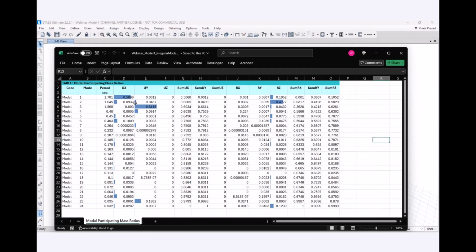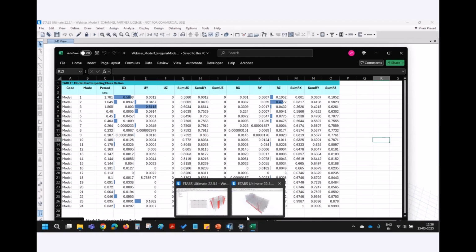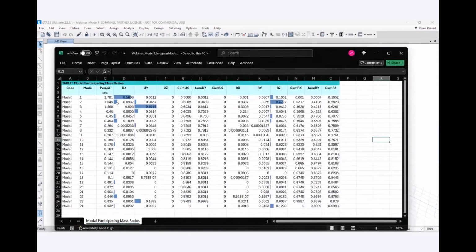to know the ranking of the first three modes in that particular direction based on the ratios. But you can see the first one, sorry, the second one is more on the torsion. This building has significant torsion. Just wanted to show a real building where this kind of situation arises. So you'll have to skip this particular mode in the summation. So this is 1, and this is 2, and this 3. This is about 55 and 10. It's just about 65%.